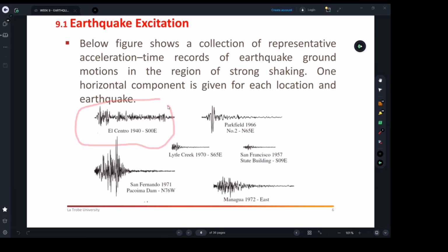Now, you see in the news when there is an earthquake, they talk about the Richter value and all these kinds of details, but this is not enough for the engineers to work with. Engineers typically need the ground motion records, something like that, to see what's going to happen to the building. The Richter gives a very brief idea about the level of damage such ground excitation will impose on a city or an area, but this will not tell you how a particular building can respond to that motion, because the Richter is just the energy that came from the epicenter, etc.